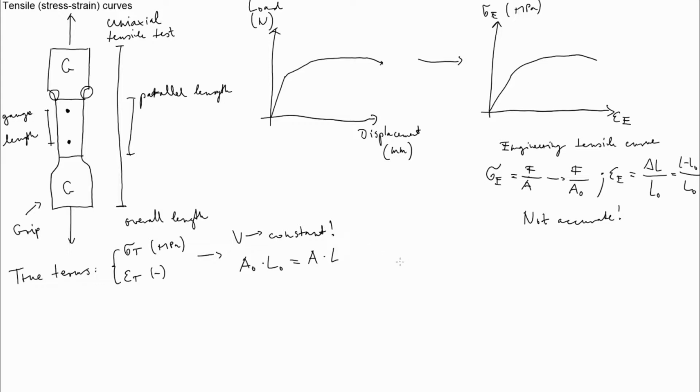And first we would like to calculate the true stress, and it's very easy to calculate it by using this equation. We just rearrange it for A, so A will be A0 times L0 divided by L, right? It's very simple. So now in general stress is F over A, right?